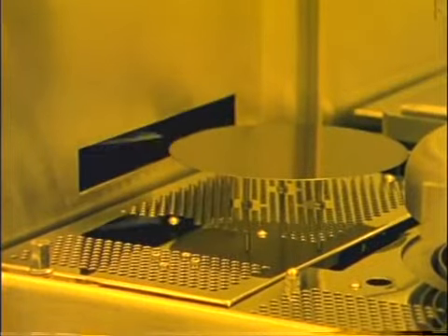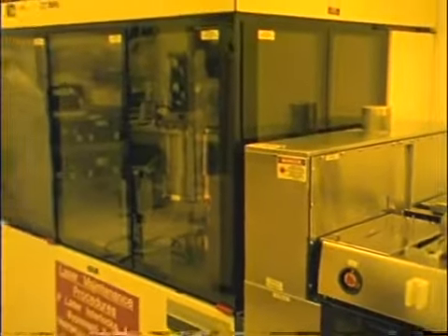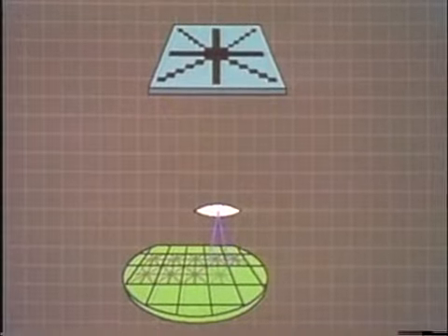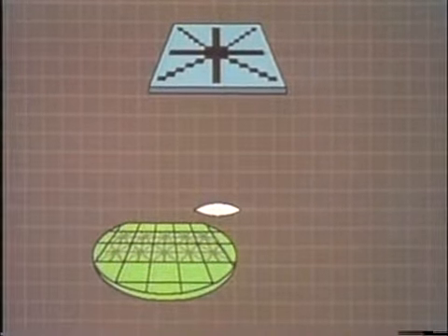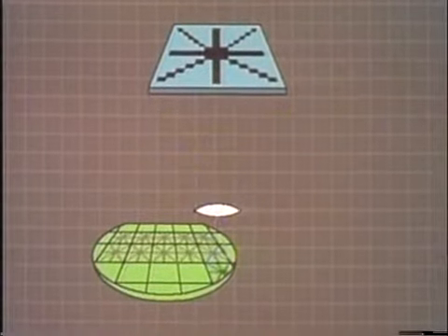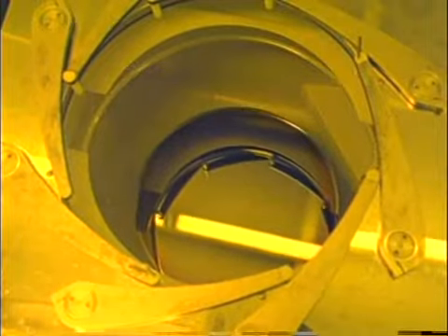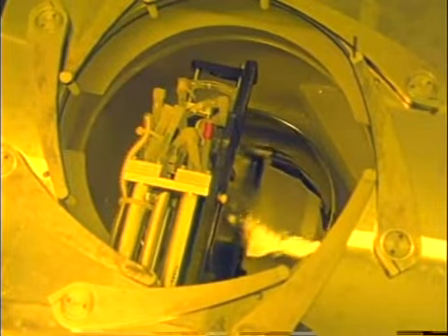The wafer then enters a computer-controlled machine called a stepper. Inside, the wafer is positioned underneath the selected mask pattern. Ultraviolet light exposes the pattern across the surface of the wafer. In this way, many chips are made on a single wafer. By increasing the diameter of the original crystal, larger wafers are sliced and more chips can be made on each wafer. The wafers are then developed.